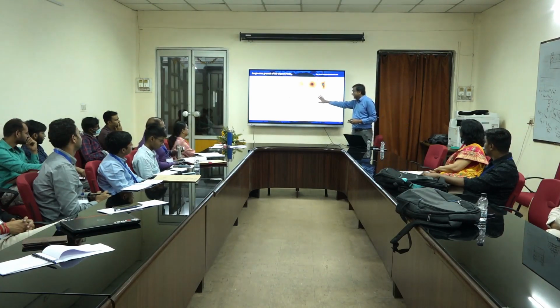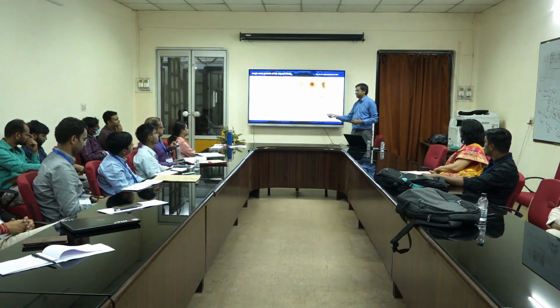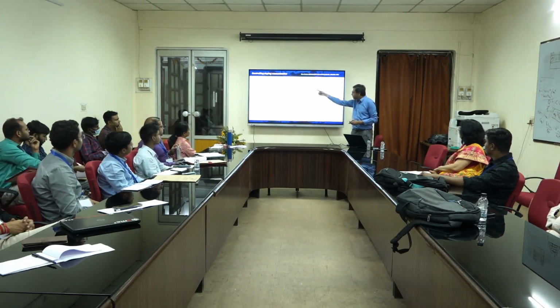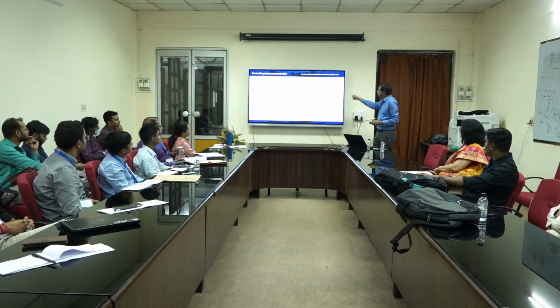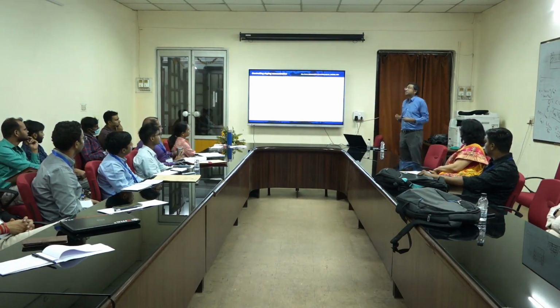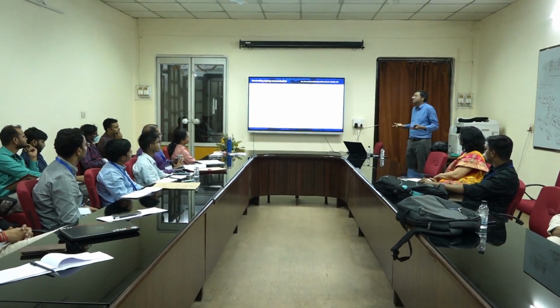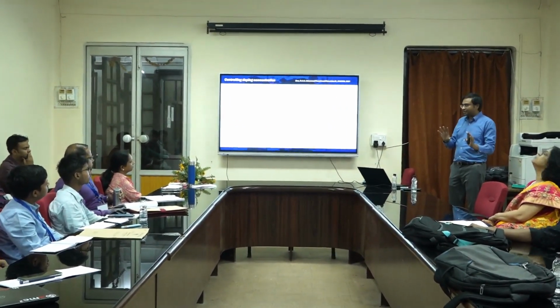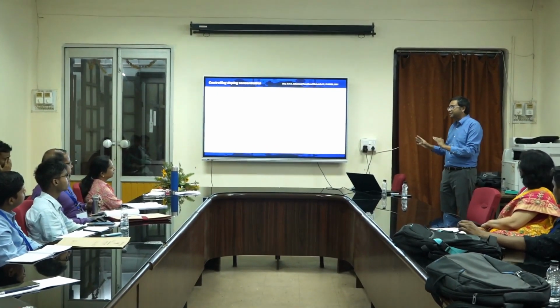Because here I can start controlling the doping percentage. This is why this came, that I can now controllably do 0.6%, 0.9%, 1.9%. So control we need to engineer eventually. Conceptually we proved that thicker layer with degenerate doping, and thinner layer with non-degenerate doping, is needed. But now we need control, and we need scaling. Scaling will come from CVD growth, and control will come from controlling the doping percentage.